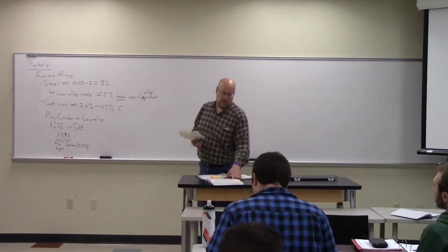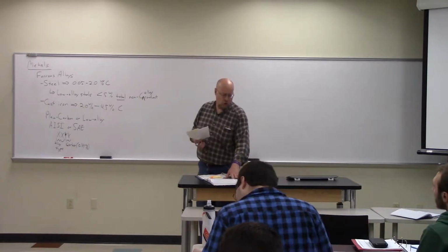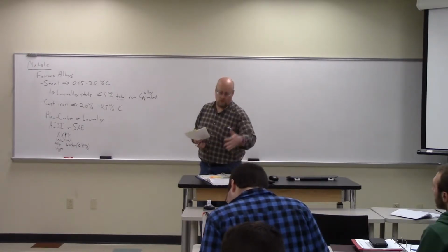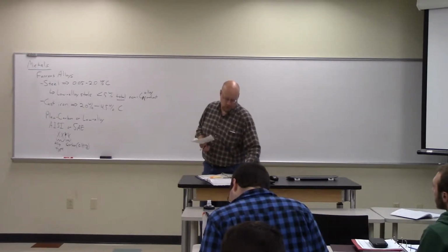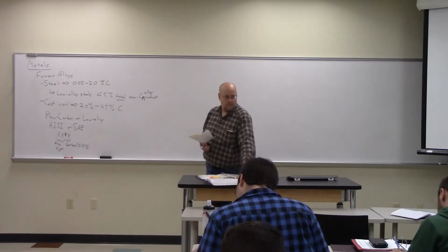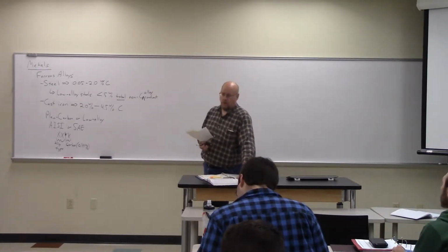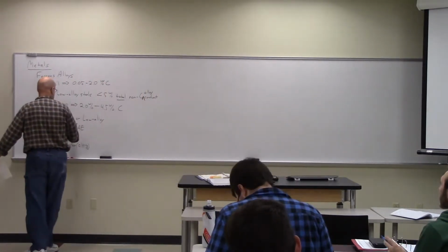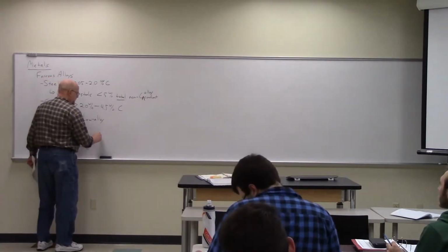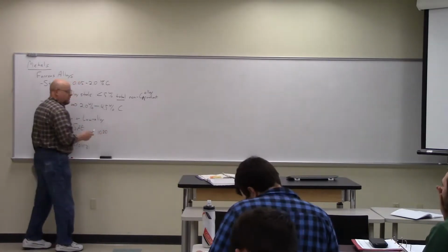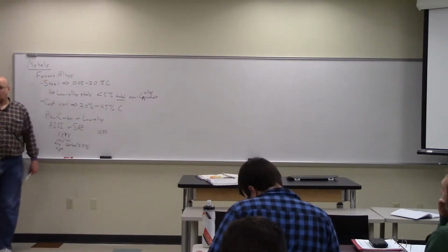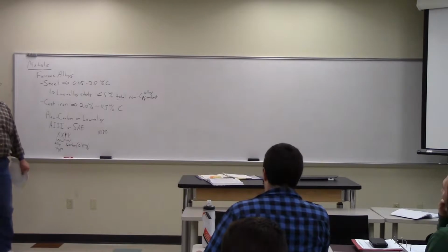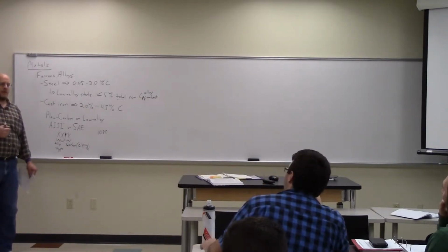There's nothing quantitative, it's just a sequential list. It's just two numbers that correlate. And then, so for instance, if I told you have 1080 steel, you know that it's a plain carbon steel with 0.8 weight% carbon.